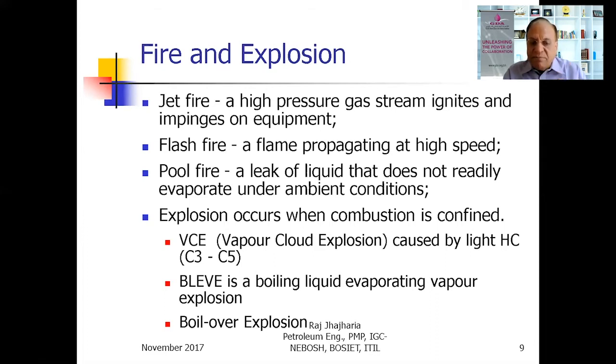And when that steam starts going, because steam now is lighter than the crude oil, it will start going through the crude oil. It will start bubbling through the crude oil. That bubbling through the crude oil will result in boiling. This is why it is called boil over. This boiling effect will make the crude oil break the roof of the tank and spill all over. And as it spills, it may catch fire. And once it catches fire, that becomes an explosion. So boil over explosion. That's also very dangerous.